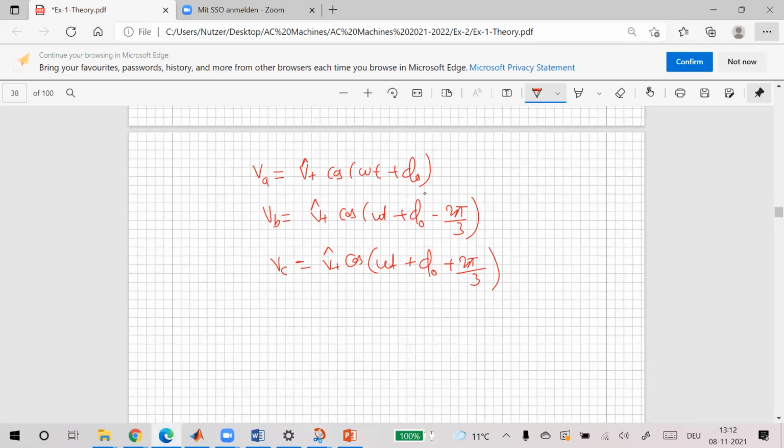And then in the fault, basically one thing will get zero. If you have a fault in all three phases, then all three can be zero. If we have a fault in one phase, let's say B phase, then this can be zero. If we have a fault in the C phase, then C can be zero. If we have a fault in A and B phase, or B and C phase, then both can be zero. And when we say fault, it's not necessary that it has to be a solid fault. It can be a fault with some impedance also. So when there is an impedance, it makes some voltage. So it's called low voltage ride through.